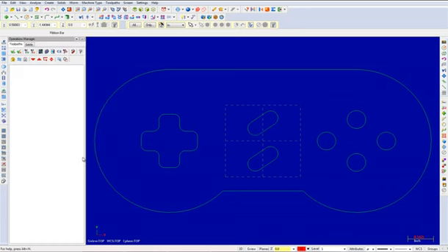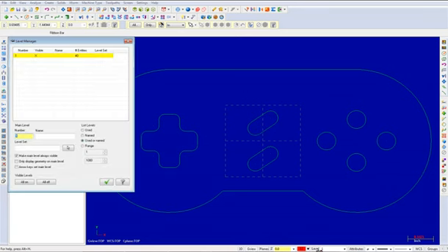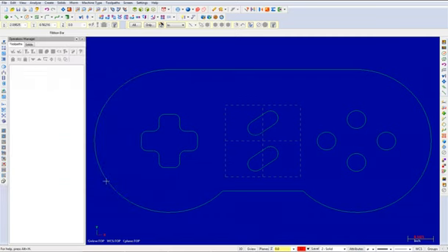From here, left-click on Level in the status bar. When the Level Manager appears, below Number, input 2 and enter the name Solid. Once complete, select the OK button to exit the Level Manager. You should note that all the entities you will create will be on level number 2. In the status bar, you should see the system color is set to number 12 and the level will be set to 2.